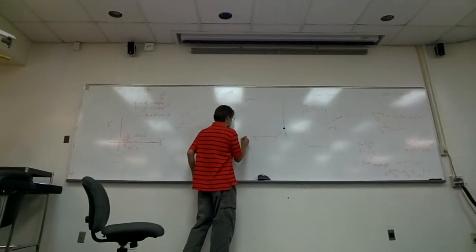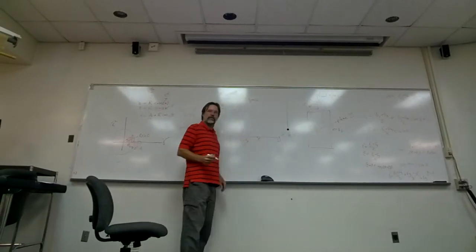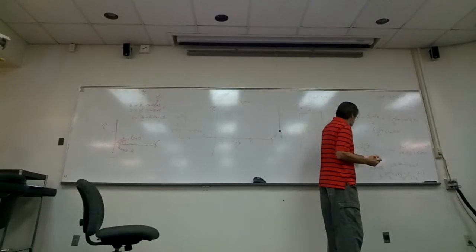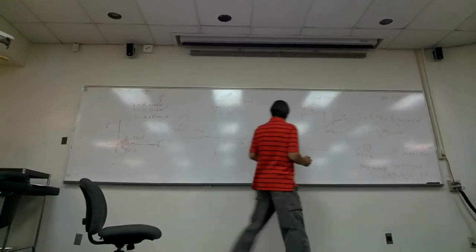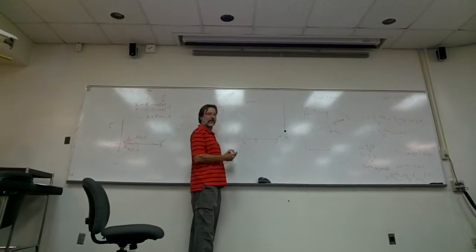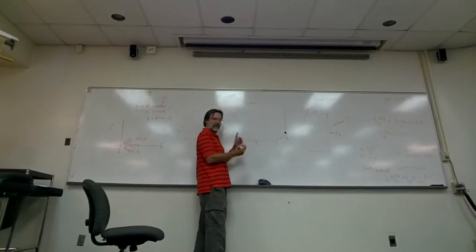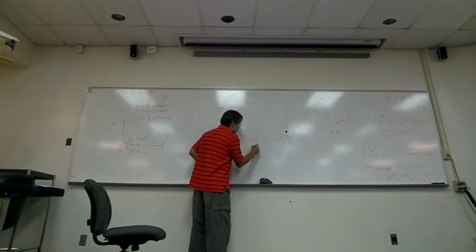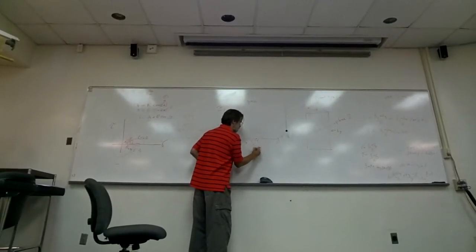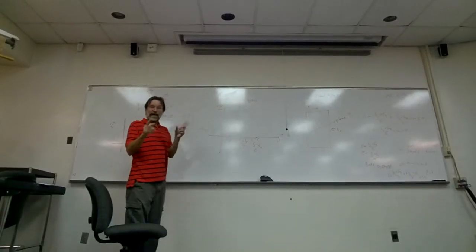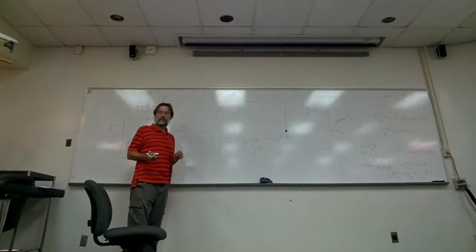That's the average, right? This value then, what's sigma 1 minus sigma 3 over 2? That's a little harder to figure out. But that distance right there is sigma 1 minus sigma 3 over 2. Back to this set over here, that's the radius of a circle.